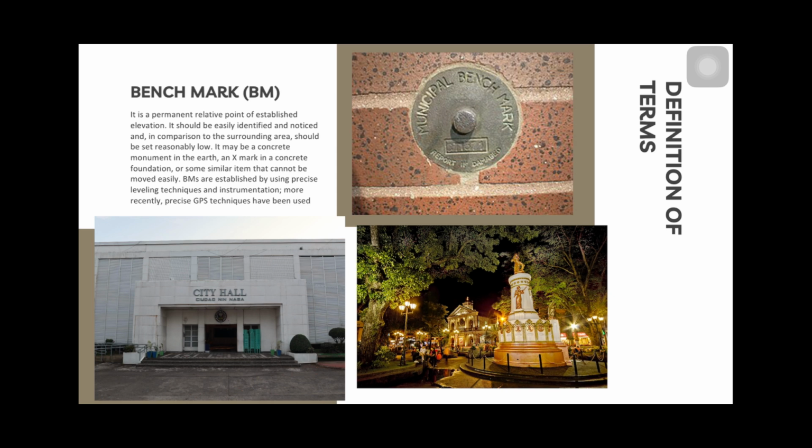According to elevation data, it stands at about 11 meters above sea level. Alternatively, if your project is near the Naga City Sports Complex, which sits around 37 meters above sea level, you could use that as a reference. Later on, if you're working on a real surveying project in the field, remember that professionals always obtain benchmark locations and elevations from official sources like municipal offices or NAMRIA.